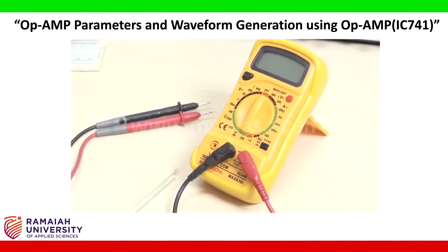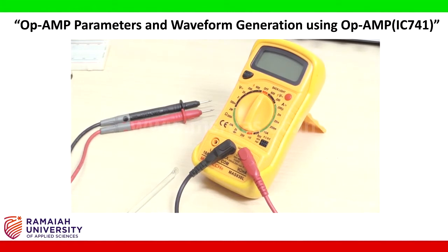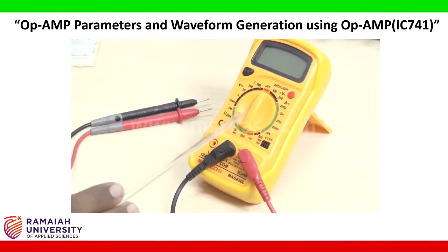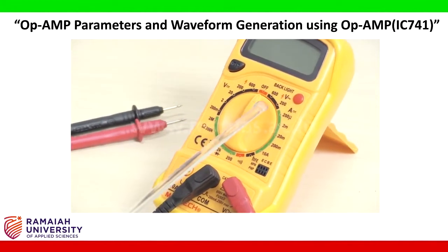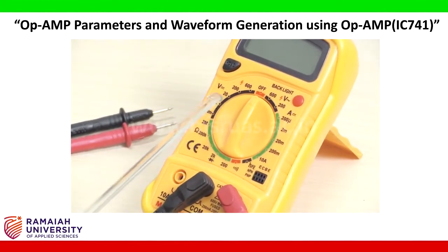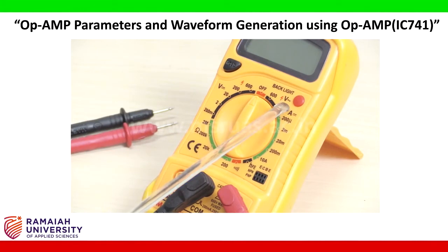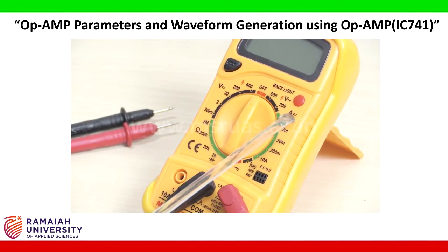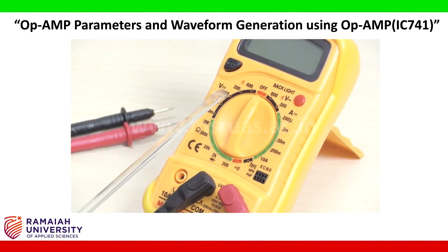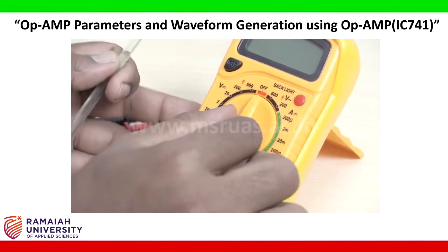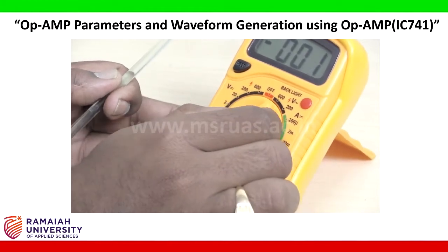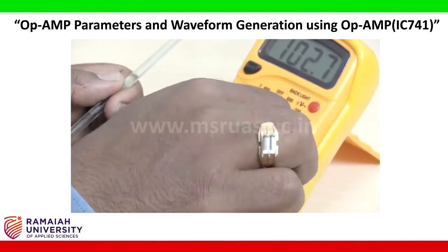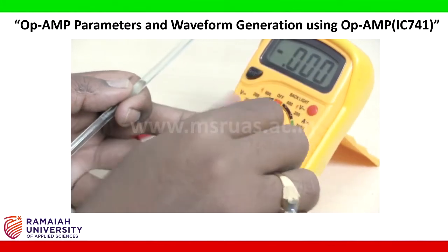Multimeter that will be used to measure the voltage and current level in the circuit. Okay, and we can measure our resistance values here. So it measures both AC and DC values. This sign indicates the voltage in AC. This indicates the current in DC. This indicates the voltage we can measure in DC. If you want to switch this on, you can turn it like this. It will switch to voltage or to the required parameter.